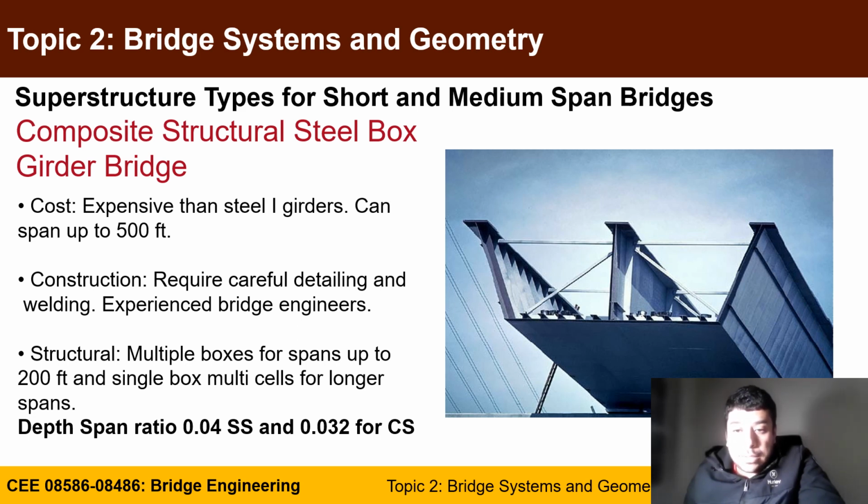So you have steel top flange, you welded with one web, bottom flange is wide, you have also two other top flanges and webs. So in this case you have three webs, and they are all welded together. And after that you have what we'll discuss later, shear studs, and those shear studs with the slab are provided to provide actually composite action between the girder and concrete.